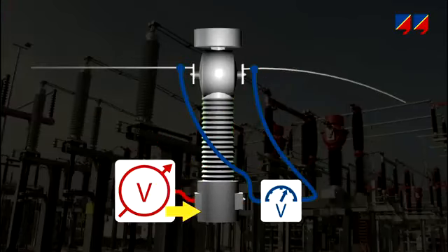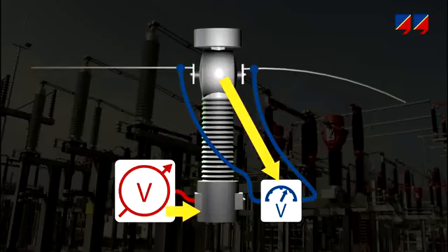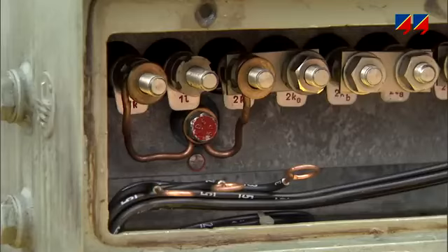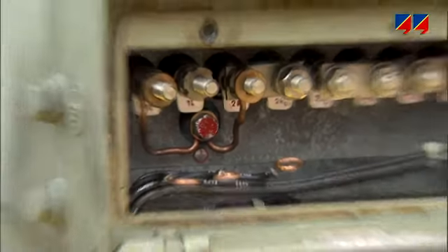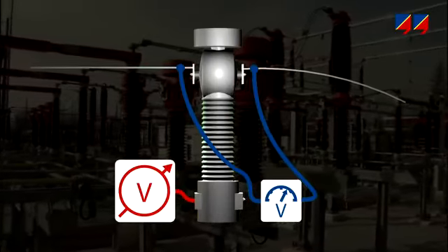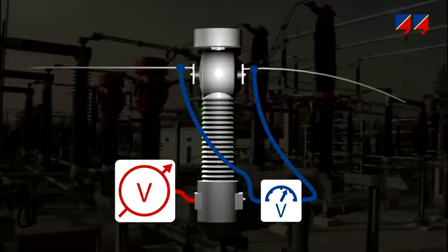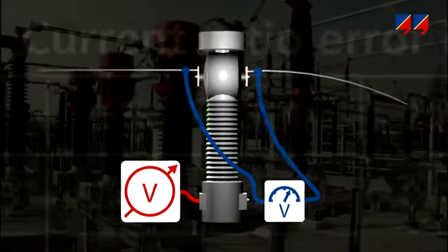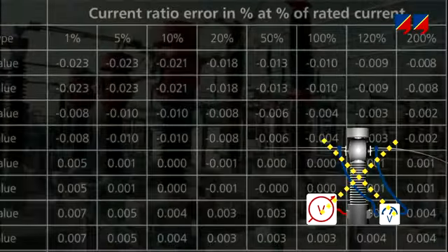Using a variac to inject voltage on the secondary side and measuring the voltage induced on the primary side allows confirmation that the protection or measurement circuit is connected to the correct CT core and tap. As it uses power system frequency, the method's accuracy is limited, as it is directly influenced by external disturbances. In addition, it cannot measure a CT's accuracy at defined current and burden values.